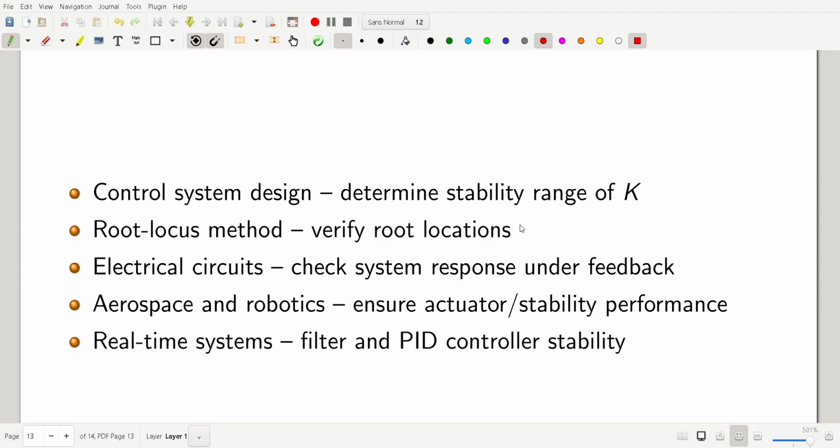Whenever our root locus crosses the omega axis, at that time we should know the gain. The maximum gain on the verge of instability is also called the gain margin. We generally find the gain margin using the Bode plot and Nyquist plot. So that's the correlation we can think of here.